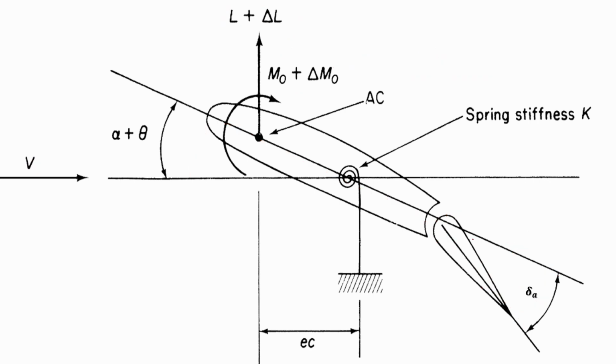Generally what happens is, because of this aileron, for example, we have a twist center here because of the hinge, and we have a lift here, right? So this lift, we are calling it delta L, and if we try to move this lift force to the elastic axis, we'll actually have a nose down pitching moment, right? We'll have a nose down tendency. The overall lift will be decreased, even though we have produced an increment in lift.